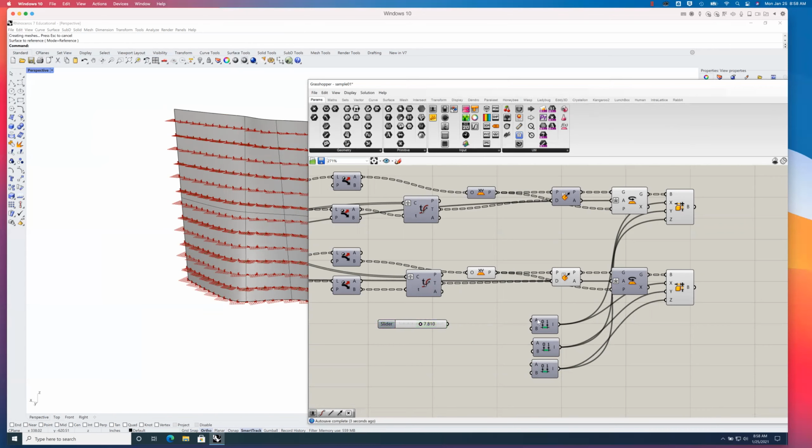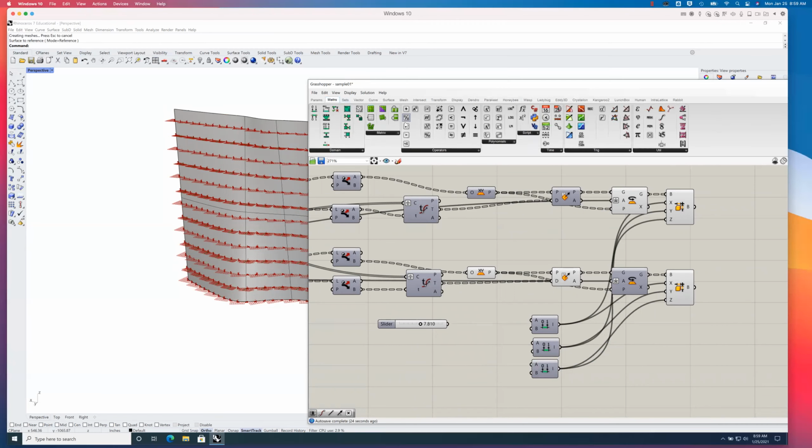It's asking for the minimum to the maximum, and before we used a -4 to a 4, right? So I think what I'm going to do is take whatever this number is as the actual dimension I want. So I'm going to divide it by 2. I'll use the division widget here. We can do simple arithmetic like that. Plug that in, divide by 2.